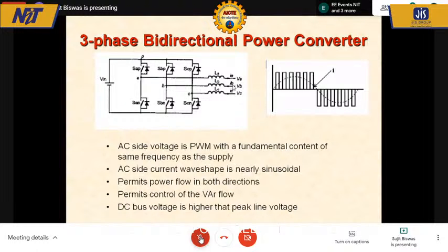So I thought I will connect the capacitor here. An inverter with an LC filter will create sine wave voltage, so this should be good to connect to the system because the sine wave voltage will not send out harmonics. Yes, you are right. But we are overlooking that the connection of the capacitor here is being made directly onto the main system, and you'll land up with the same problem that I showed there.